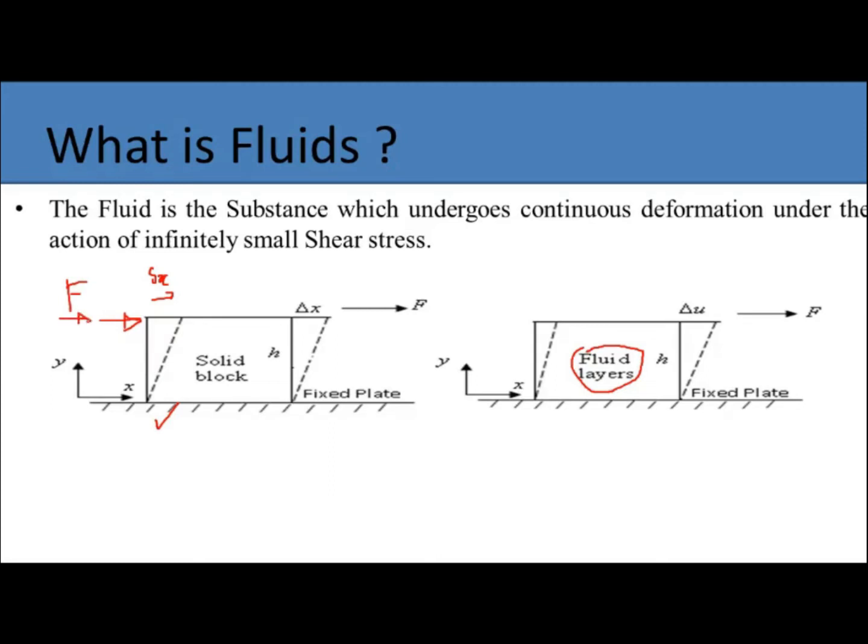आप F की वैल्यू बढ़ाओ, suppose पहले आपने 5 किलो न्यूटन अप्लाई किया, तो 0.1 mm डिफॉर्मेशन हुआ. Then आपने 10 किलो न्यूटन कर दिया, so basically वो 0.5 mm हो गया. Then आपने 100 किलो न्यूटन अप्लाई किया, तो 1 mm डिफॉर्मेशन हो गया. So if you apply the force F, there will be a limited deformation del X, and the more the value of F, the more will be the deflection del X. Now what will happen if you remove this force?